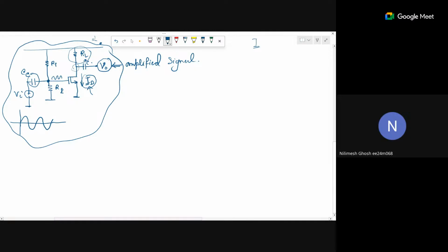So to know this particular thing, we have to model. What we know now is some KCL, KVL, some Ohm's law. This thing we know, right? Now we have to analyze a particular circuit using these only. In this circuit, the MOSFET is a device. To apply KVL, KCL and Ohm's law and analyze the circuit, we have to model the particular MOSFET in such a way that we can apply them to the circuit.